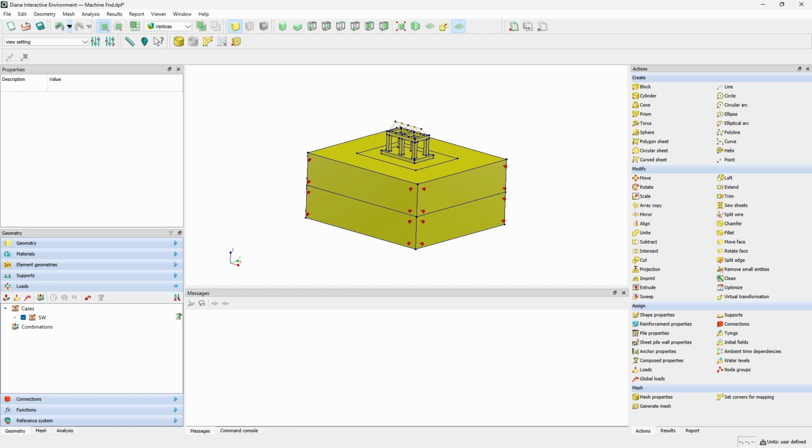To simulate the forces caused by the unbalanced rotation of the compressor, we are defining 4 separate load cases. Each one represents a different phase of the rotation. For each load case, we attach a time factor curve that captures how the direction of the force changes over time as the machinery spins in the model. For this purpose, I need to define the load for the low pressure compressor and the high pressure compressor. Let's start with the low pressure compressor.